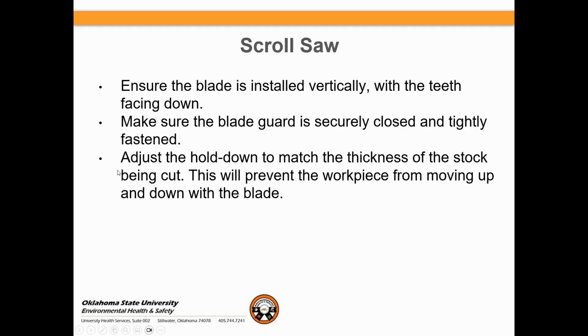Ensure the blade is installed vertically with the teeth facing down. Make sure the blade guard is securely closed and tightly fastened. And then another thing is to adjust the hold down to match the thickness of the stock before being cut. This will prevent the wood from moving up and down with the blade.